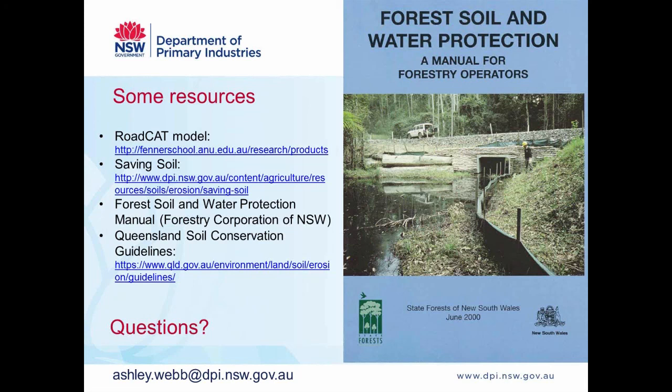So I've applied this here in a forest environment, because that's obviously where I ran those models, but some of the work that came out of the Victorian government and also the ACT area after the wildfires around Canberra showed that there were some major changes in the hill slope hydrology following those wildfires. So you create hydrophobic soils, you remove the surface vegetation and so on, and obviously these models don't necessarily apply for a period of time. So yes, that vegetation cover can play a major role.